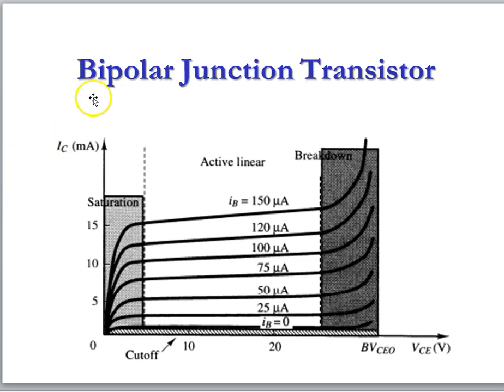So if we look, for example, at the bipolar junction transistor, often referred to as the BJT, which is fundamental for all computer designs, also MOSFETs, and we look at the current versus voltage relationship in this BJT, each of these curves is related to a different base current, and they're very nonlinear over the range of voltage from 0 to BVCEO, the breakdown voltage.